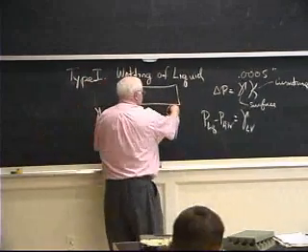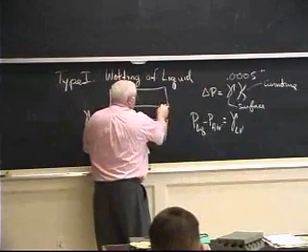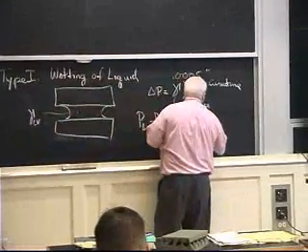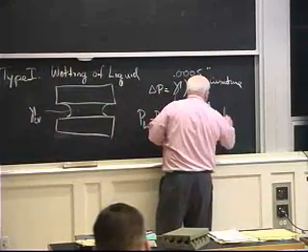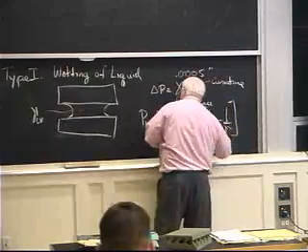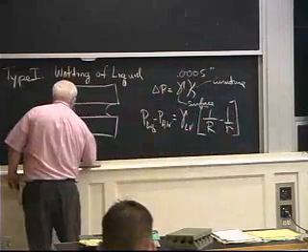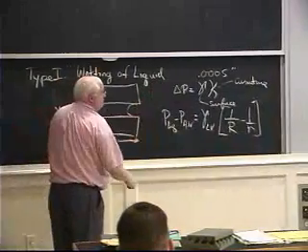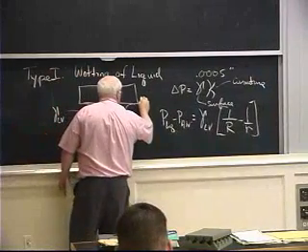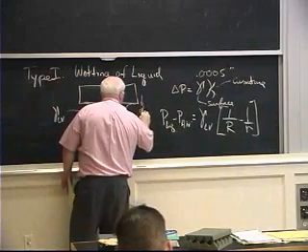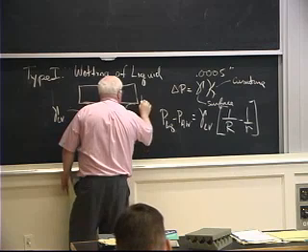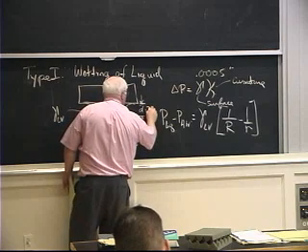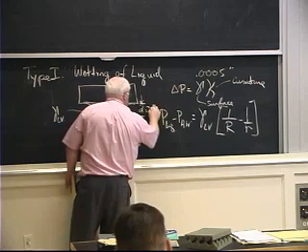And it's this surface energy here that's pulling these things together, and that's going to be equal to the curvature, which is 1 over big R minus 1 over little r, where big R is the radius of these, if these are two circular discs, and D is equal to approximately 2 little r.